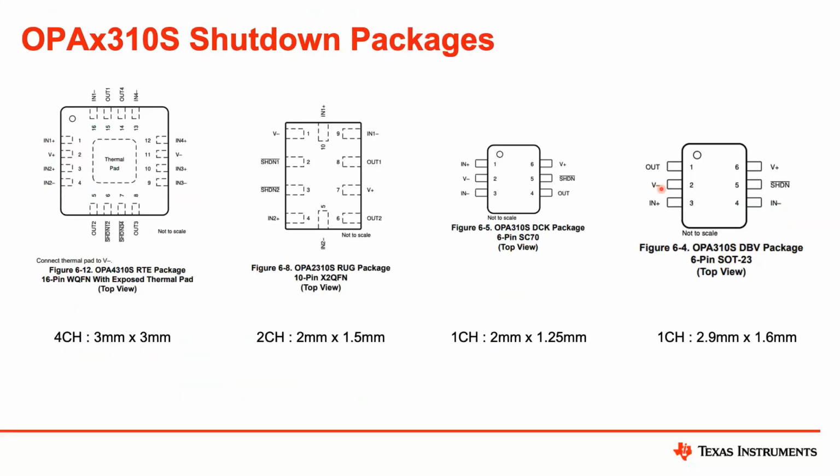Lastly, with this fail-safe ESD and very good enable and shutdown quiescent current performance characteristics, we are still offering OPA310 in some of the smaller packages out there. In the 4-channel, we are offering it in a 3x3 RTE, and for a 2-channel, we are offering it in a 2x1.5 RUT package. This enables you to use OPA310 in small size battery powered applications, really taking advantage of the quiescent current consumption in enable and disable modes.